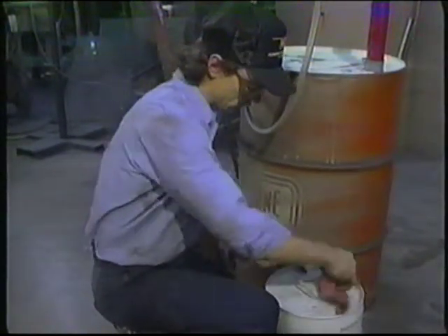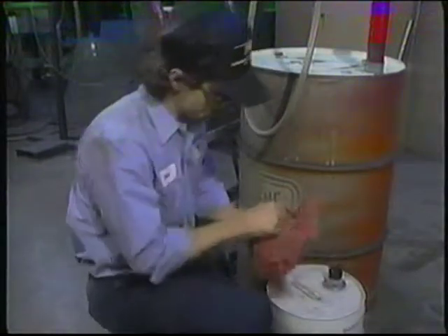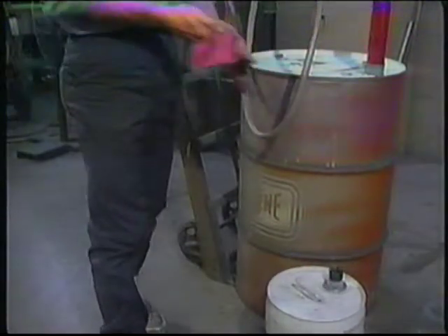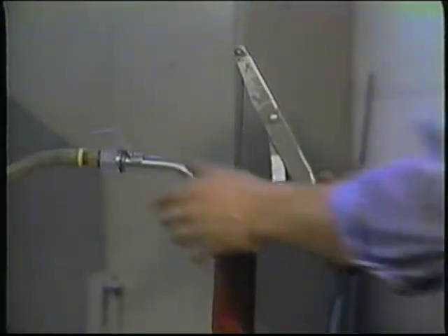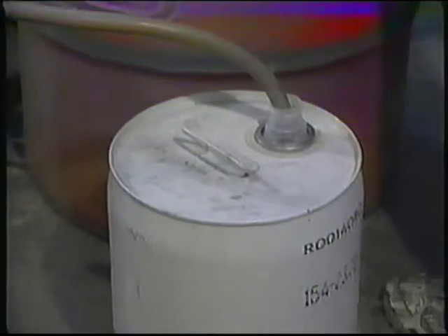Finally, adding new fluid may be a source of contamination. Clean buckets, hoses, funnels, pumps, even clean hands are a must. Even the fluid itself can be a problem. For example, new hydraulic fluid straight out of the drum has usually only been filtered down to about 50 to 70 microns. It may not have been filtered at all.